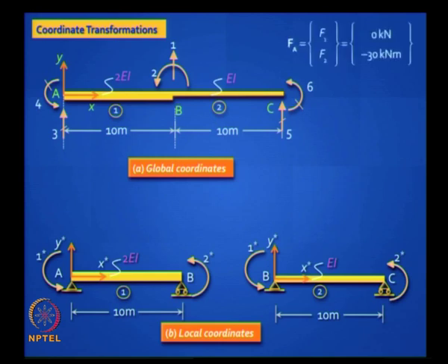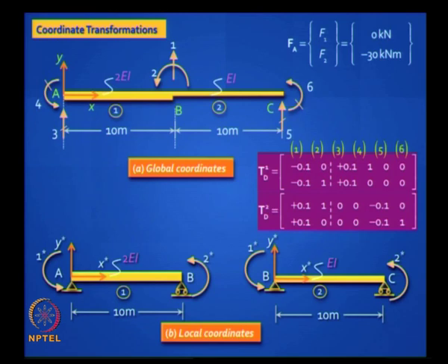So let me help you. First of all, the given loading is, you have a nodal moment 30 kilonewton meter. So this is what you will get. Let us do it together, listen carefully. D1 equal to 1, this goes up, it causes an anti-clockwise chord rotation in element 1 and causes a clockwise chord rotation in element 2.